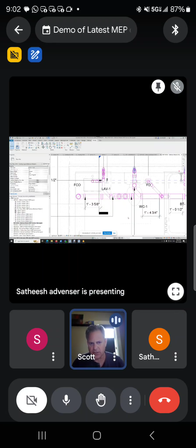Does that make sense? Because there's a glue joint, and it's going to slip in there a 1/2 inch to 3/4 of an inch on either side. So the part cut is going to be 1.5 inches longer than 1 foot 3 5/8. Do you see what I'm getting at?